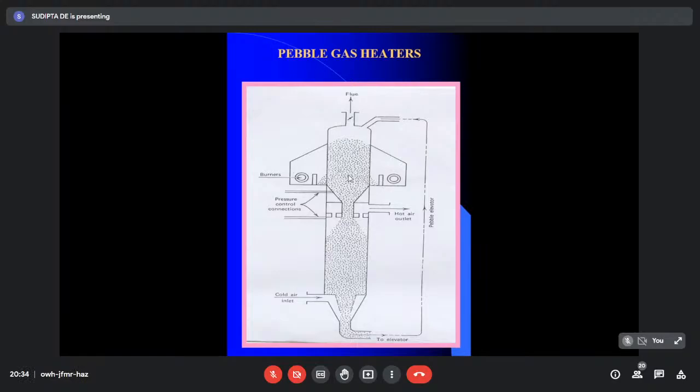That means unless the specific heat of these pebbles is high, it cannot have a large heat content. For the same, two things are very important. One is the temperature, another is the heat content. Your heat transfer will happen due to temperature difference. Unless you have a good temperature difference between the heat exchanging air and the pebbles, you will not have sufficient heat exchange. And simultaneously, during that heat exchange process, temperature will decrease because it is rejecting heat. But unless it has got sufficient heat content, air cannot get it. So how much is the specific heat capacity of the pebbles is also important.